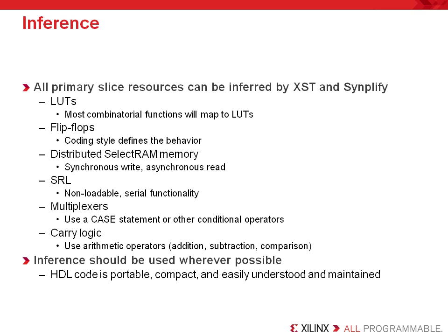Similarly, MUXes should use a case statement, and carry logic should use the proper arithmetic operator in the HDL code to infer it. Don't code for an XOR functionality with your HDL code and expect to get carry logic inferred.